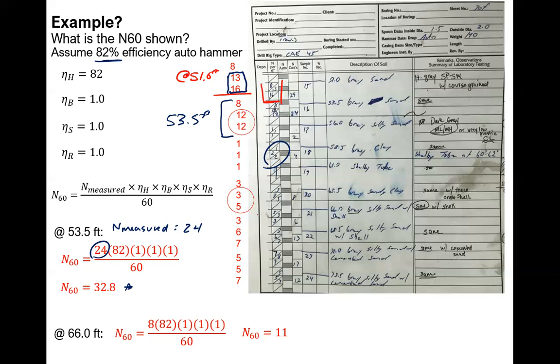This is a common thing entry-level engineers would do. They take these reports and then they would write down, calculate the N value associated with each soil layer here. And then they would make remarks and observations based off of the soil here. So that's where you'd see the classification. So right here, like I was saying, this is an SP-SM, this is an ML-MH. And then we would do further lab testing to actually classify it either an ML or an MH and so on and so forth. So there's a homework problem that you obviously need to know this for.